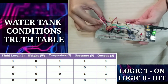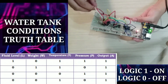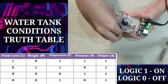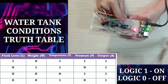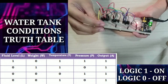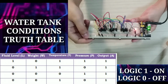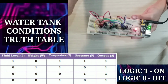Lastly, for our fourth condition, if the tank condition is that we have our fluid level at logic 0, meaning we have a low fluid level, let's put it on the ground. And if we have a low weight as well, so this blue wire here, let's put it on the ground, and we have a high temperature, or this yellow line here is at logic 1 connected here on the other end, our output will be at logic 1 as well, meaning the alarm will turn on. That's why the LED turns on.